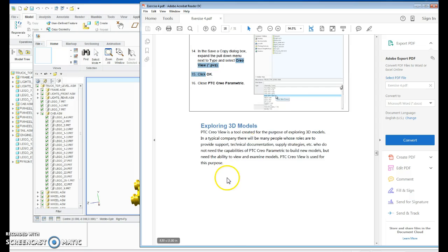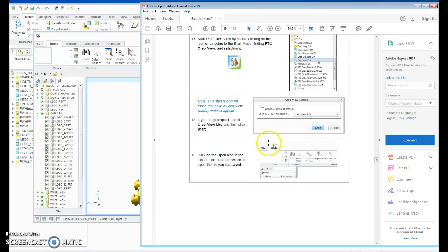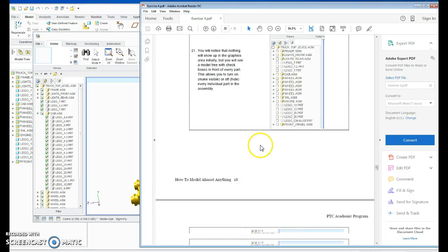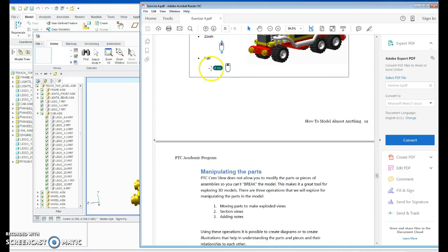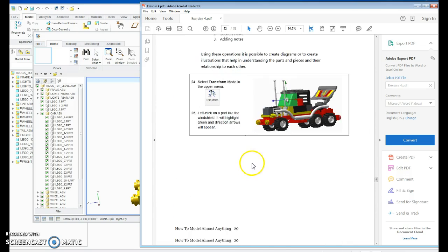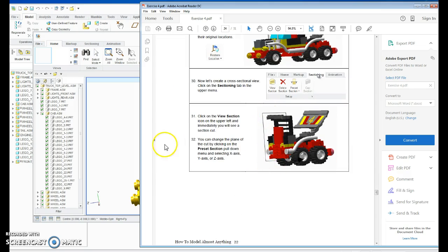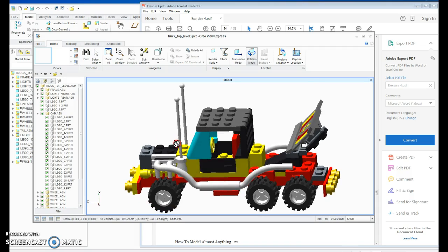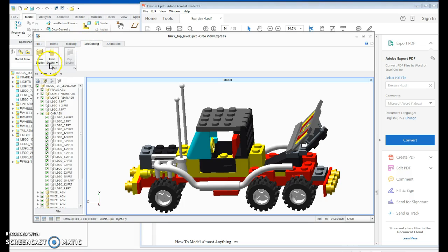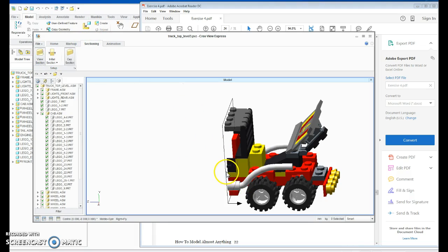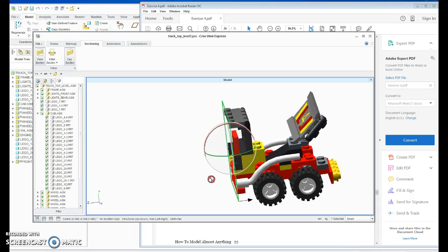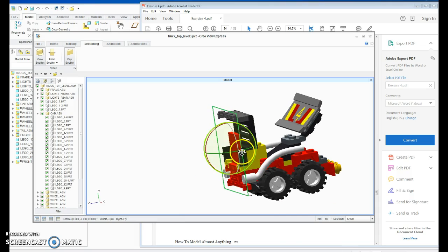Now, play around with that, and then the next thing that you actually want to do is, we did all this with the same basic commands. The difference being you can add momentum, and what you want to do is view section. It kind of gives you an MRI view of your part. So we want to look at the different sections, and we can view section. What it does is it places this slicing thing here, and essentially we can slice this down.